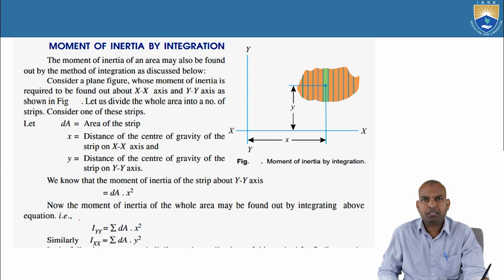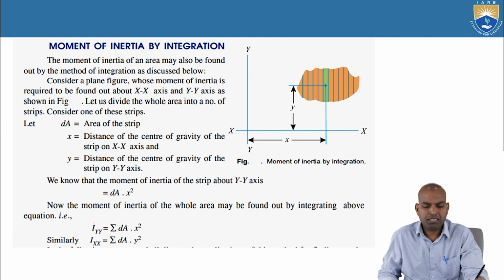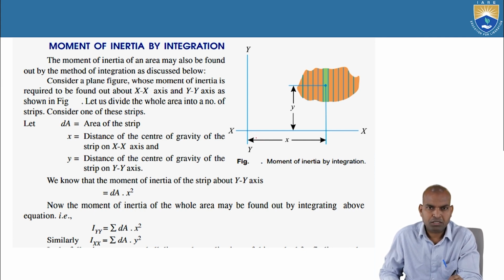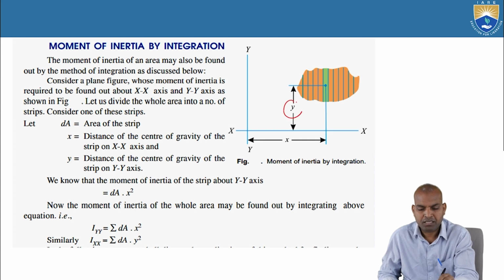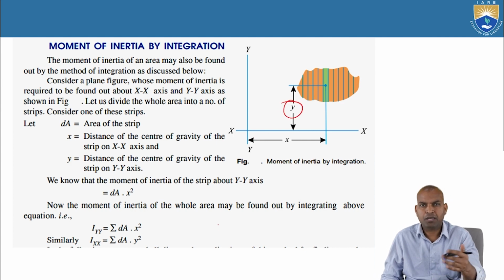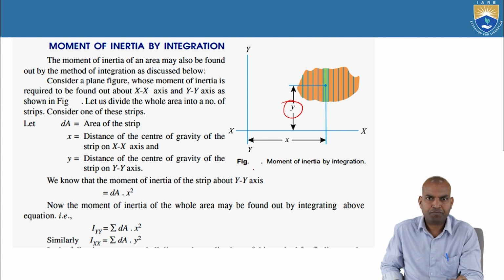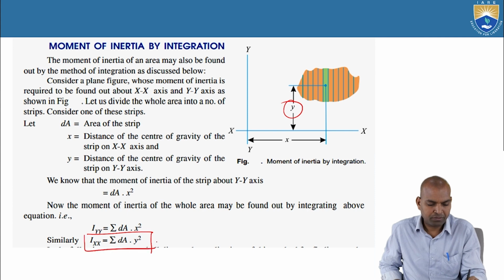So we studied the parallel axis theorem, and we also studied the perpendicular axis theorem. About axis XX, the moment of inertia Ixx equals sigma dA y square, where the distance is the perpendicular distance y.